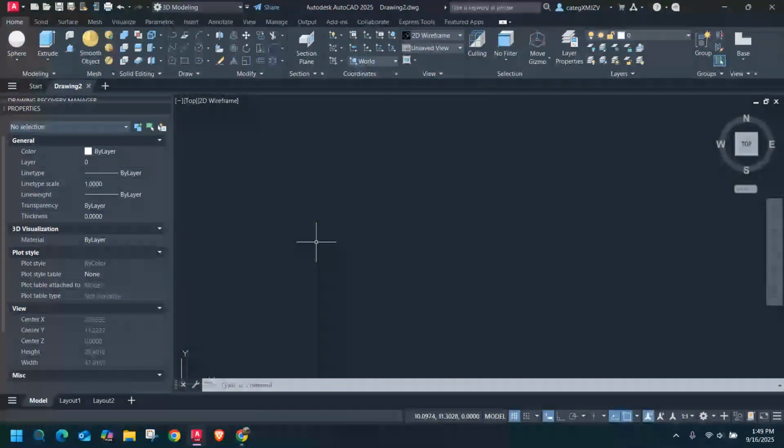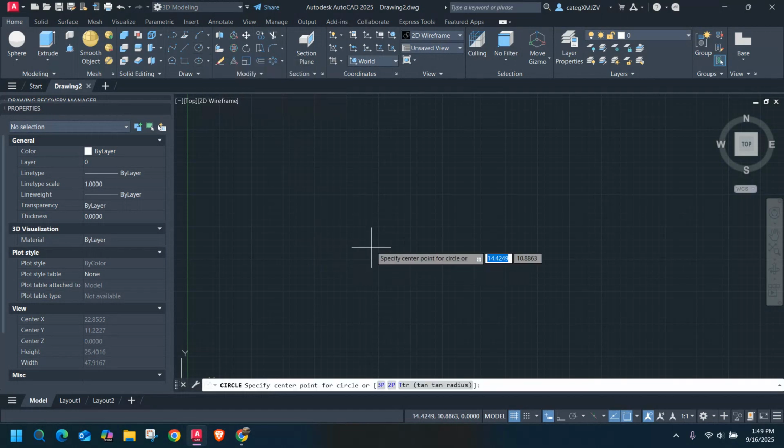So I want to show you how to create a fan blade so that you get the concept of intersect. Intersect is creating a 3D object that is not along a single plane. We've typically just done an extrusion or a press pull and it's on a single plane. However, we want to start working with more organic shapes. You're going to need to understand intersect and how to do that. So let's do a fan to begin with.